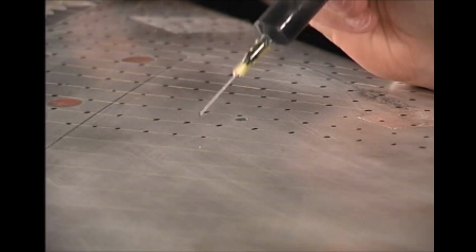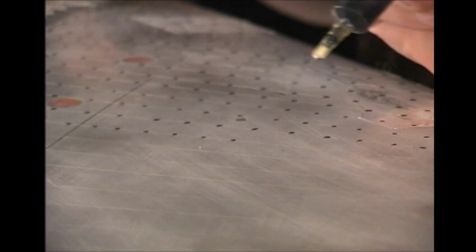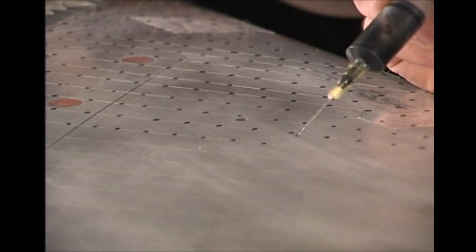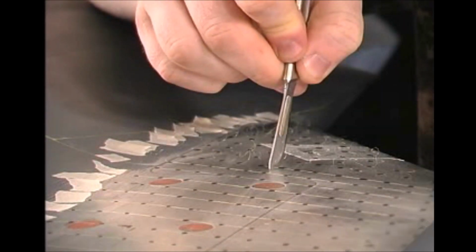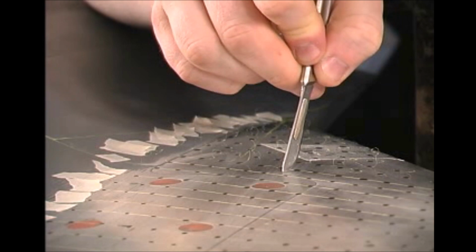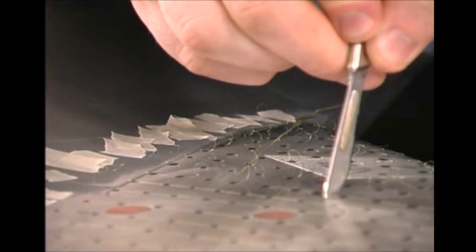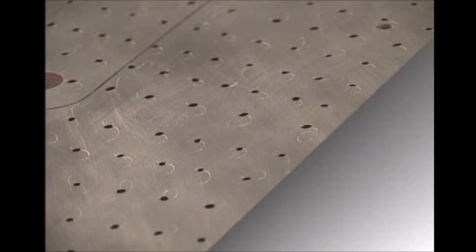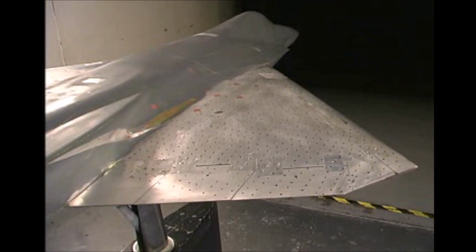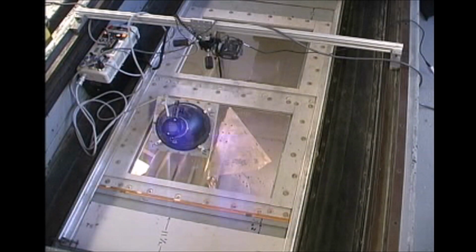A third technique of on-body flow visualization is known as tufting or tufts. In general, this means to attach tiny strings to the model, which again will be deflected in the direction of the streamlines. The trick is to make the tufts as small as possible so you don't influence the flow field. The problem is that the smaller you make the tufts, the harder they are to see. So one way around this is to use what are called fluorescent mini tufts.